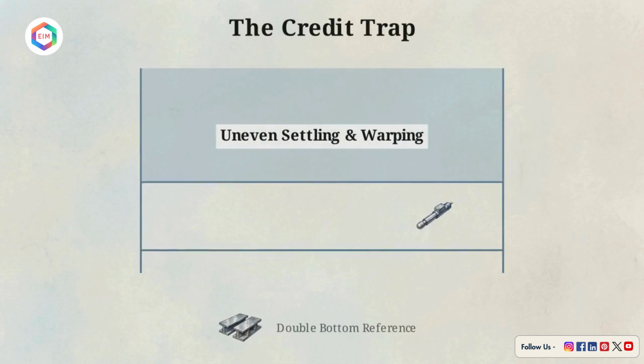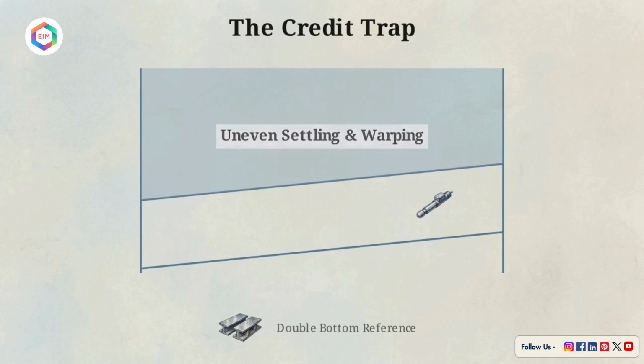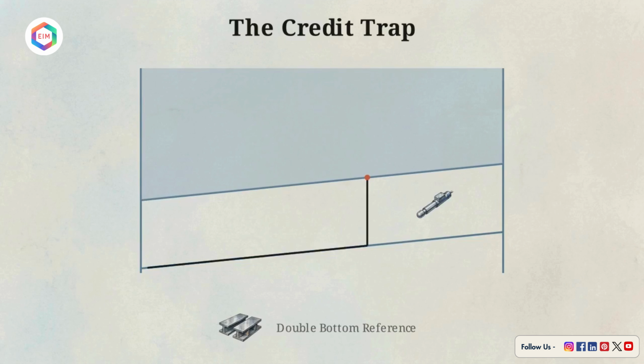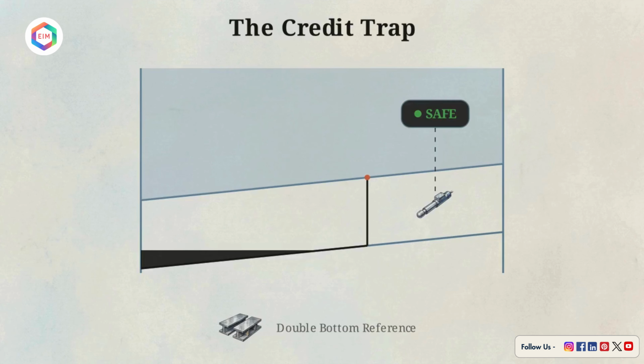An interstitial leak detection port that has never registered fluid fails to prove the floor is sound. The port could be blocked, or the fluid could be pooling in a different zone. Relying on a lack of data to calculate remaining life, without verifying the cathodic protection or the drainage design, is a failure of engineering logic.